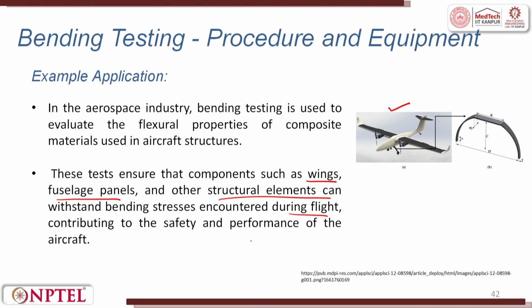So based upon these specific criteria, material can undergo testing up to a predetermined load or strain threshold or until the specimen experiences complete failure. The measured properties of this material are flexural stress, flexural strain, flexural modulus, flexural yield stress, and all those are calculated using this test. All those are then determined using this test.